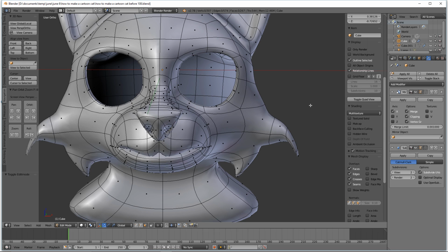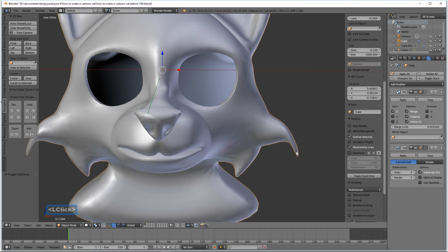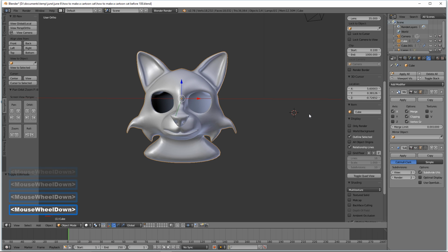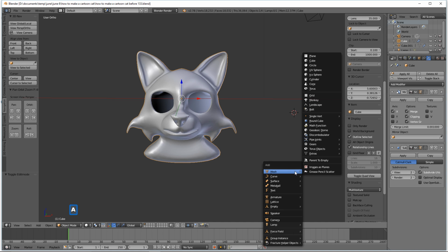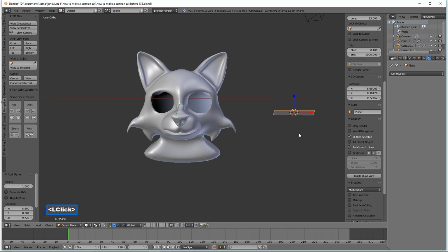Okay, here we are back in Blender. I'm going to click here, then click here to go to object mode. I'm going to roll the mouse wheel to zoom back. Okay, with the 3D cursor here, what we want to do is hold shift, press A. This brings up our add to menu. We then want to go to mesh and then select plane to bring a plane in. We're then going to press R to rotate on the x-axis 90, then enter to rotate the plane.